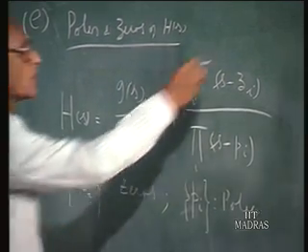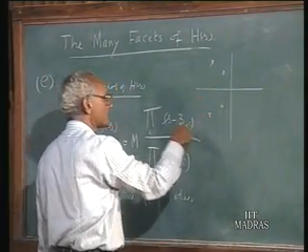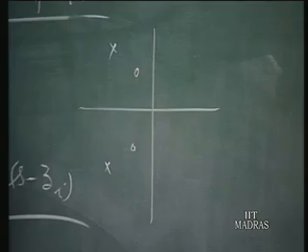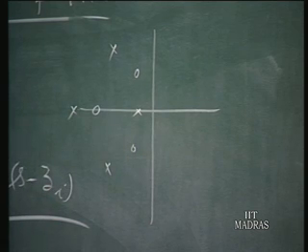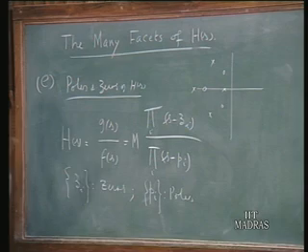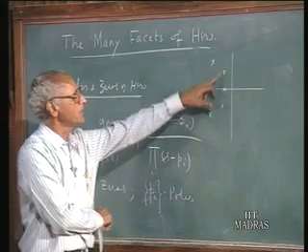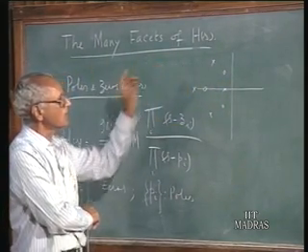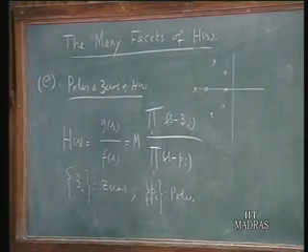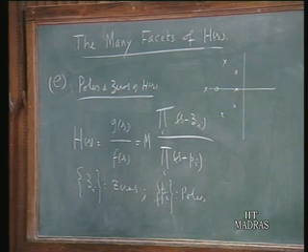The poles and zeros are generally represented in the complex plane. The zi locations are indicated by zeros, pole locations by crosses. And it has to be kept in mind that since G(s) and F(s) are polynomials with real coefficients of s, whenever a complex pole occurs, its conjugate also must be present. Similarly, a complex zero is always accompanied by its conjugate. That means complex zeros and poles occur in conjugate pairs, not singly. As far as the real poles and zeros are concerned, there is no problem. They can appear with unit multiplicity.